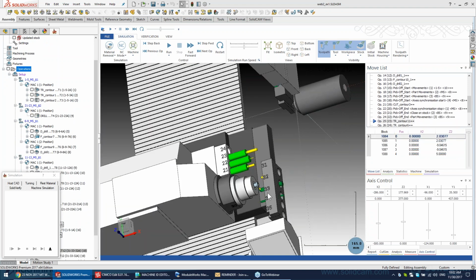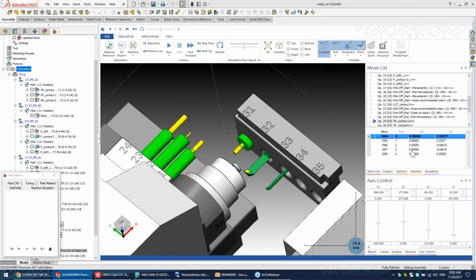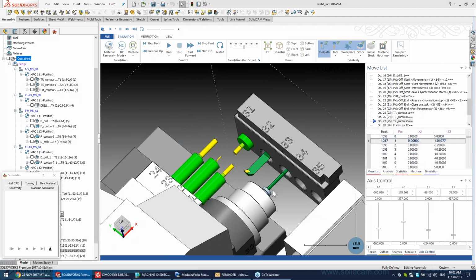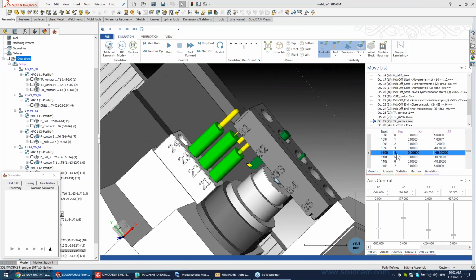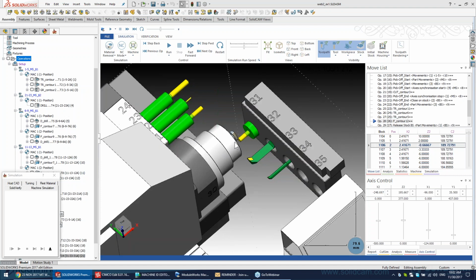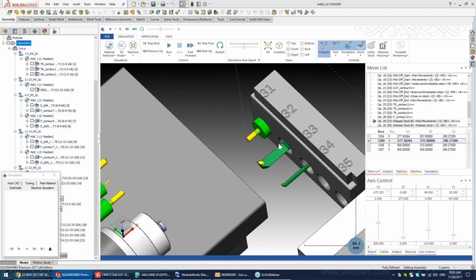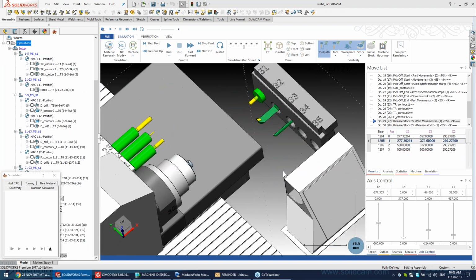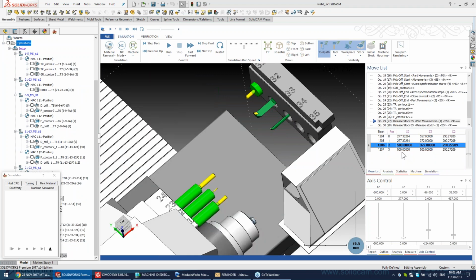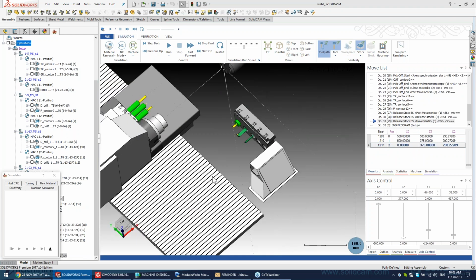Now, with the part on sub spindle, we continue to work on this fixed tool post, turning and internal turning. Also, we can use a milling tool and the part is going to the part catcher. We release the stock from the sub spindle, and the process is done.